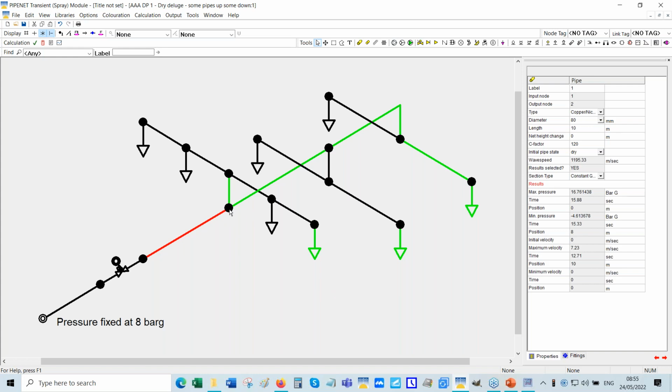In other words, the elevation difference between the location of the nozzles and the deluge valve, keep it as low as you can, because an elevation change in that pipe can lead to very long discharge times. Okay, so that's the main point about this example here.